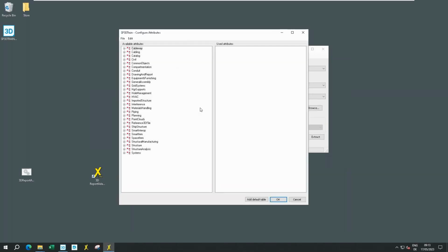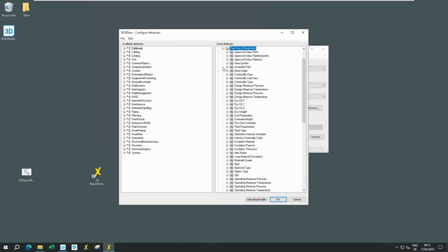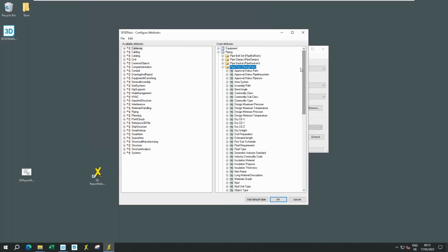When we look at the attributes, just what I have shown you in my slides, to show you how it works in reality. So we have here the piping table, and in the piping table we have all the different predefined object types, like gasket, clamps, the parts itself, components, implied items, everything you have in piping. Okay, and underneath you have your single predefined attributes, like a commodity class or something like that. This is a catalog instrument.